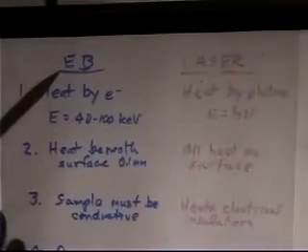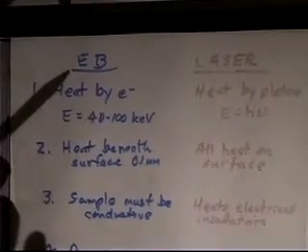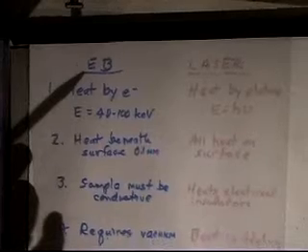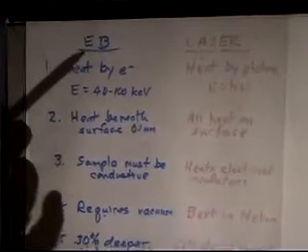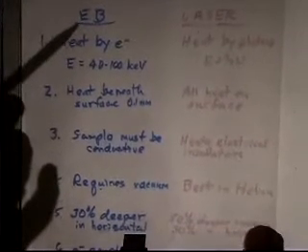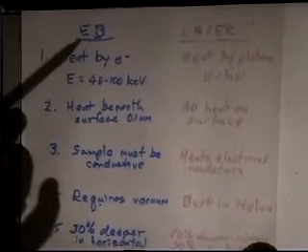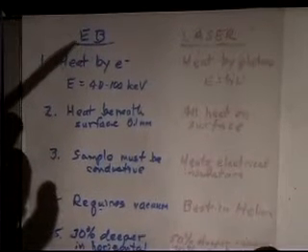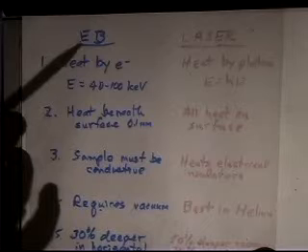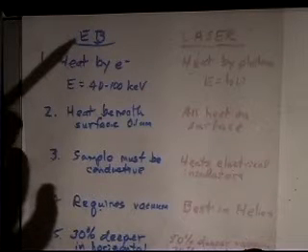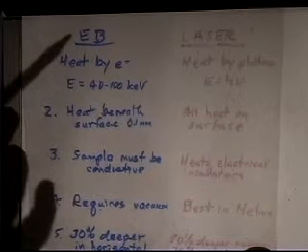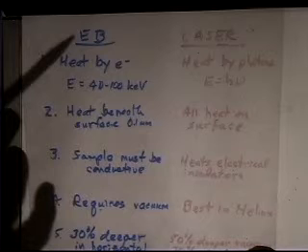Typical electron beams have a hard time giving you much more than 10 to the 7th or 10 to the 8th. But again, in pulse mode with very high megawatt beams, which we don't use for lasers but use for particle beam weapons, you can also get something like 10 to the 10th. When you start getting to 10 to the 10th watts per square centimeter, you're not just drilling holes, you're ablating the surface.